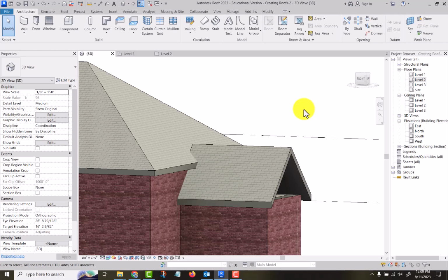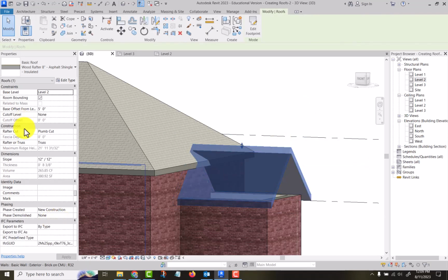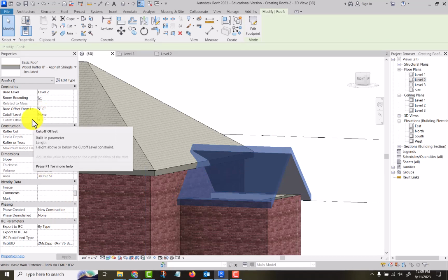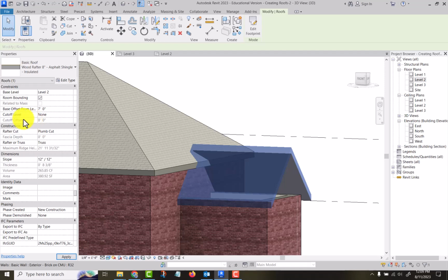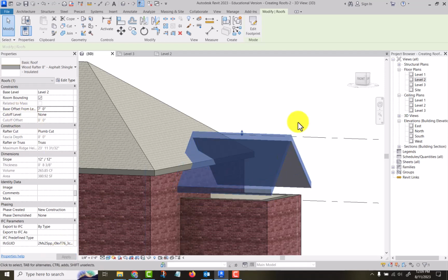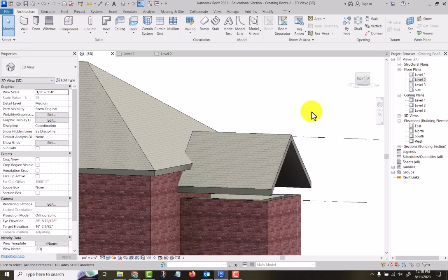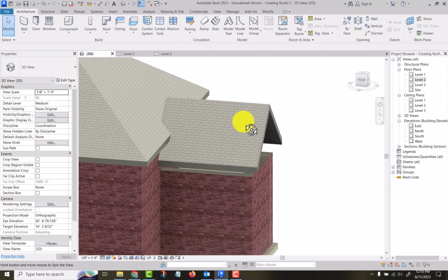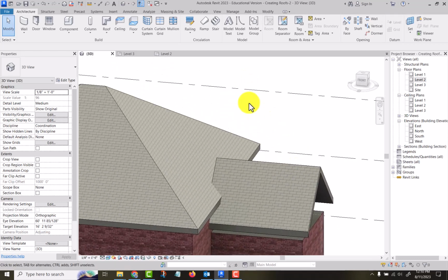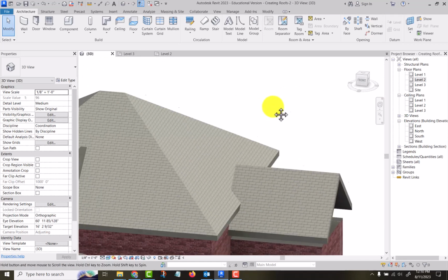Okay, this is not very obvious here. Let's go ahead and bump that higher just for giggles. We'll go 7 feet. All right, so I moved it up 2 feet. So I could raise these walls up 2 feet. That's fine. What I want to show you is how to join roofs that aren't made at the same time. And so we have 2 roofs here.